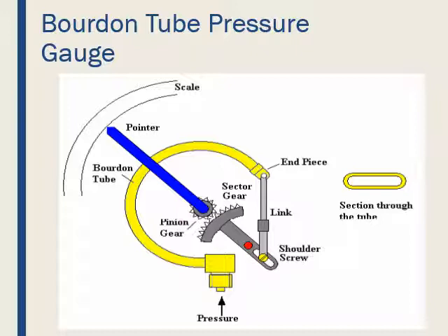A tube of elliptical cross section has a smaller volume than a circular one of the same length and perimeter. When connected to the pressure source, it is made to accommodate more of the fluid. The resultant of all the reactions will produce maximum displacement at the free end.